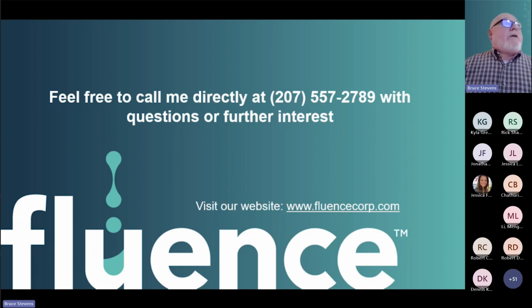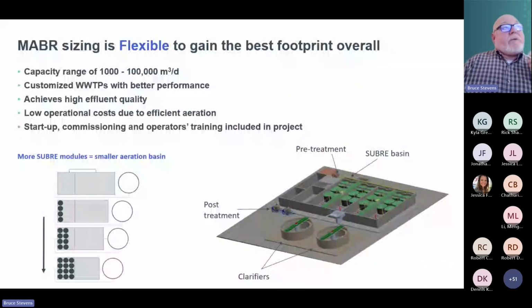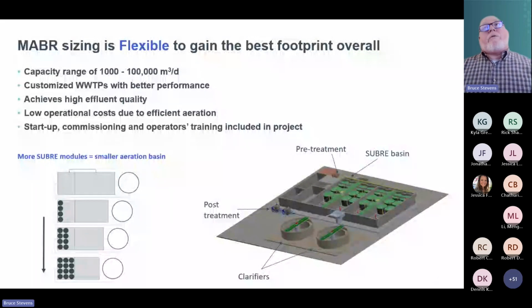When we talk about the pre-treatment required, we have specific design limits for the technology. So when you look at a plant like we have here, all these facilities have regular pre-treatment going in up front, and that includes grit removal and FOG removal.